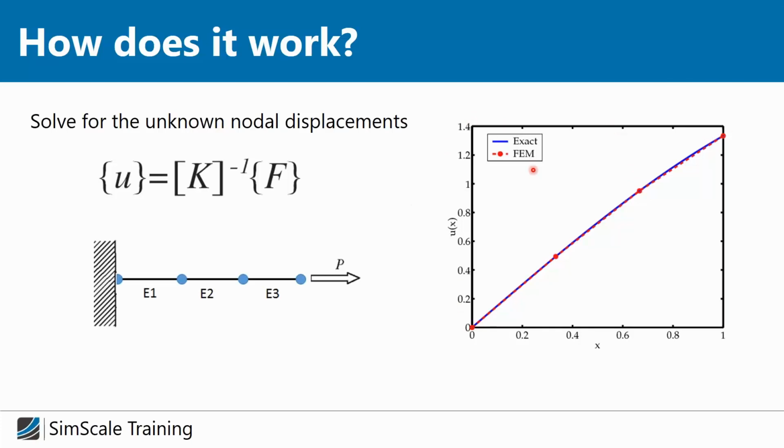In the end of the day, in advance, you should have a rough idea about how your physics are looking like, and you use more points and more small elements there where you expect to have large deformations, and where you expect to have very low or small deformations, you can use less points.